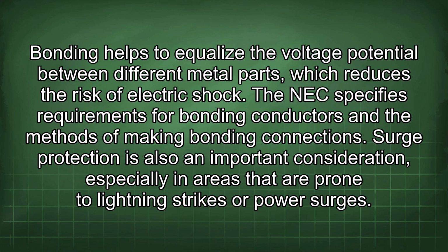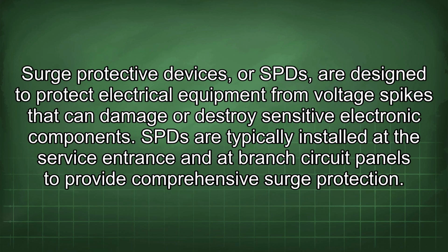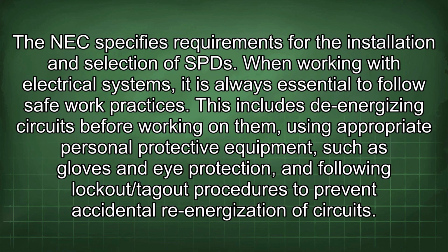Surge protection is also an important consideration, especially in areas that are prone to lightning strikes or power surges. Surge protective devices, or SPDs, are designed to protect electrical equipment from voltage spikes that can damage or destroy sensitive electronic components. SPDs are typically installed at the service entrance and the branch circuit panels to provide comprehensive surge protection. The NEC specifies requirements for the installation and selection of SPDs.